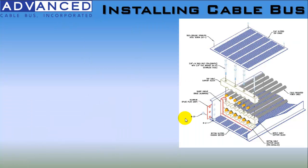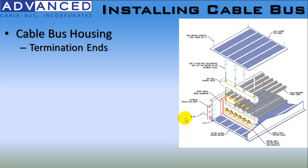Once we ship the cable bus and it is received and checked out at the job site, the time will come where the installing crew will proceed with the installation. For the cable bus system, prior to installing the cable bus housing, the routing must be cleared and the structural supports need to be in place. Then you begin with laying in the cable bus housing bottom sections from one termination end to the other, including the termination accessories as needed.